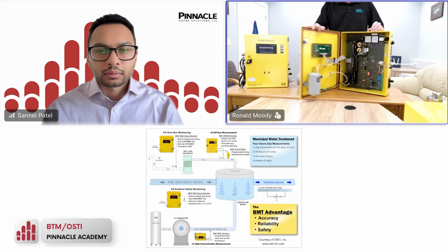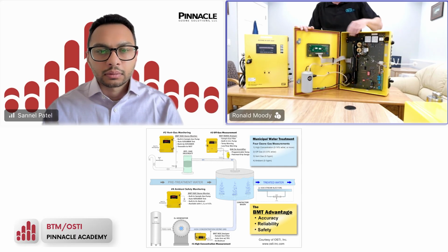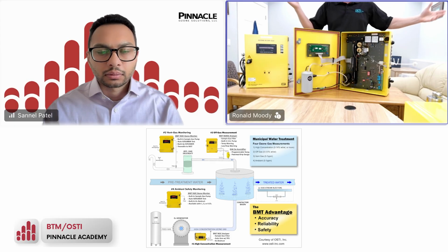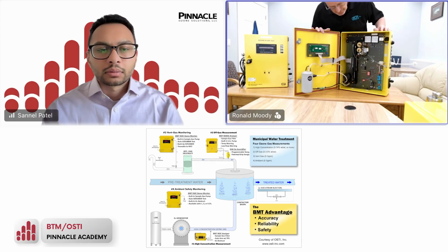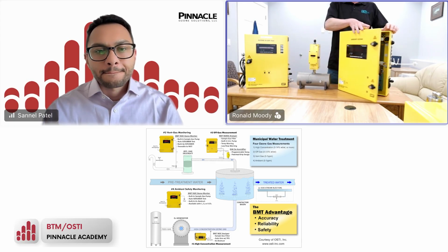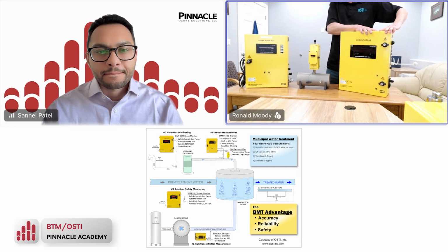So ambient ozone analyzers have a continuous duty sample gas pump. It's constantly sampling from a space, just atmospheric, okay? It does have a small catalyst destruct inside the unit, and it is self-regulated in terms of flow, so roughly a liter per minute, and monitored for low flow.